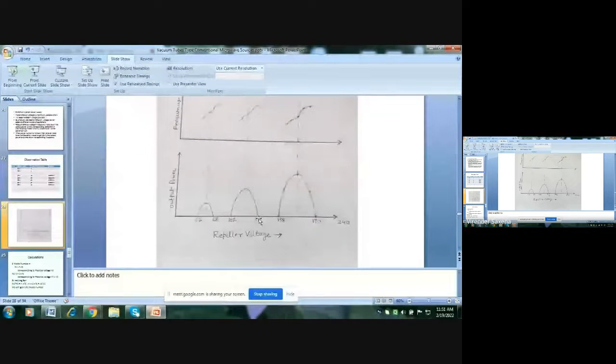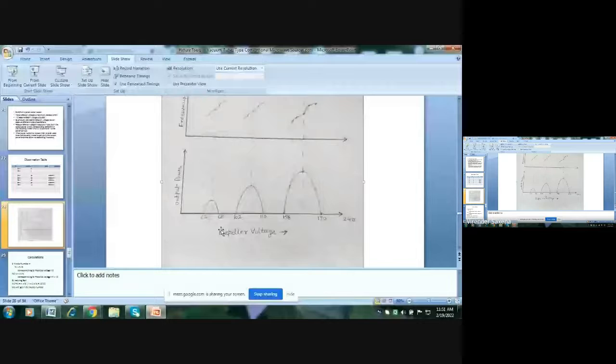And then from 110 volt, if we reduce the reflecting voltage, then once again we'll get the second mode, means we'll get favorable interaction, and this power varies from a certain minimum value to a maximum value and then reduces to 0. So this is the second mode.